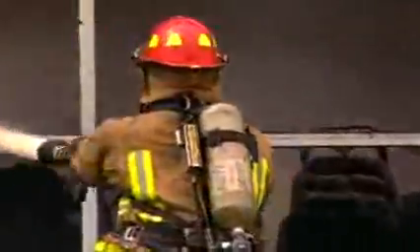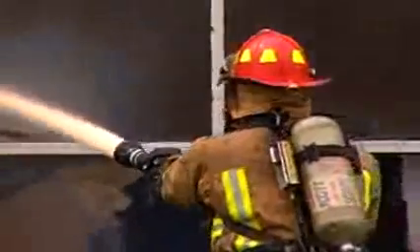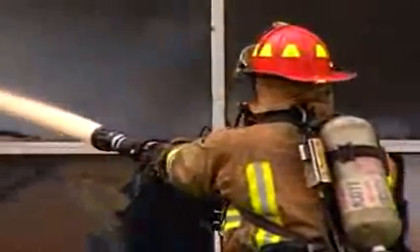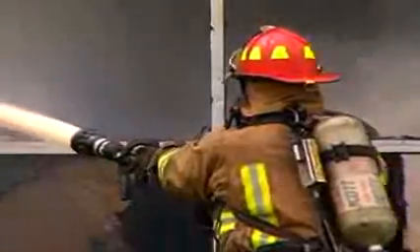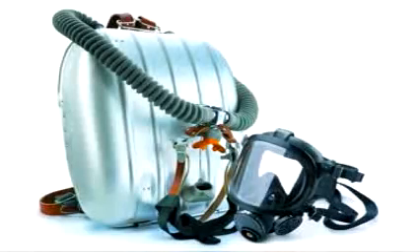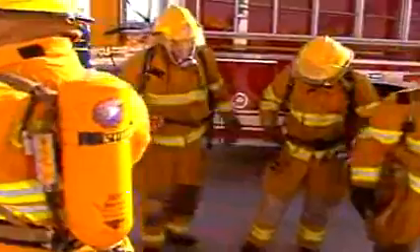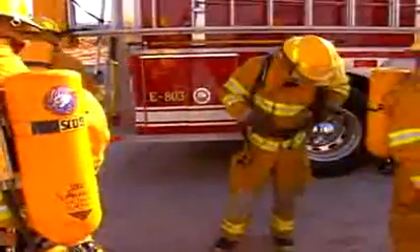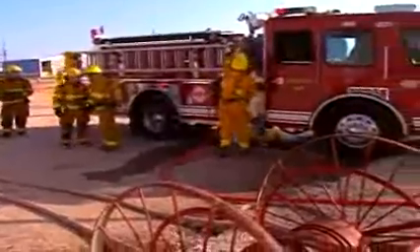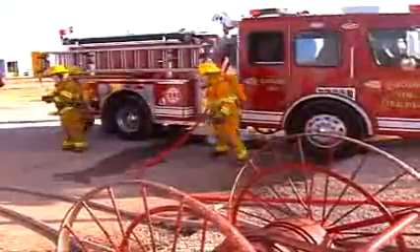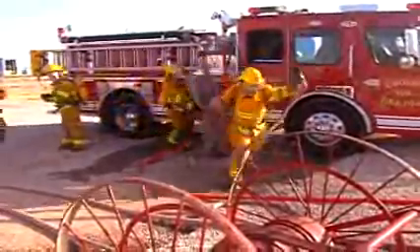The SCBA consists of a wearable, clean air supply pack and doesn't restrict movement with a hose connection. The closed circuit type can provide breathing air up to 4 hours. The open circuit type only provides air for 30 to 60 minutes. And finally, the SCBA is normally used when there is a short time needed to enter and escape from atmospheres which are or may be immediately dangerous to life and health.